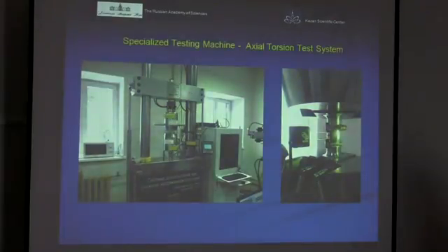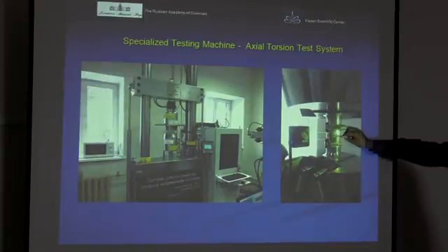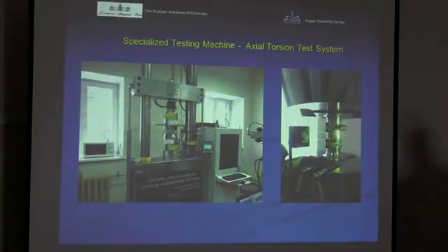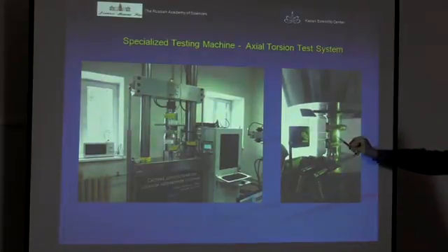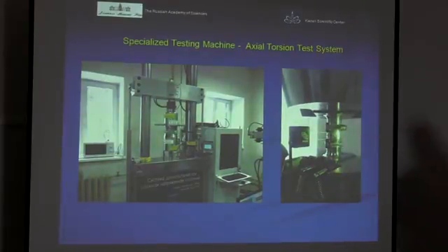So, now I am going to explain the results of our test experiment. When we carried out our test, we simultaneously fixed the crack opening displacement on the free surface of the specimen, and by using an optical microscope, we measured the crack length on the free surface of all tested specimens.